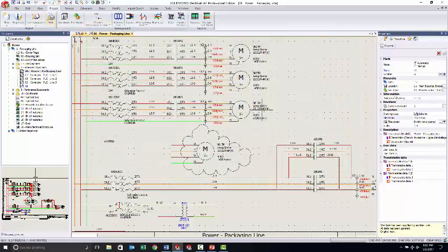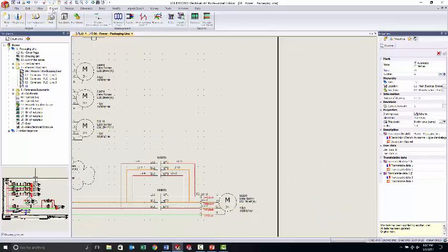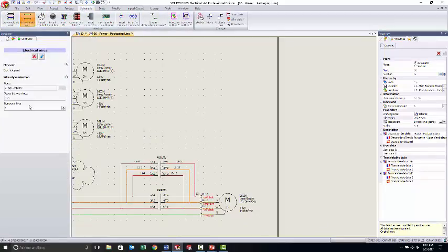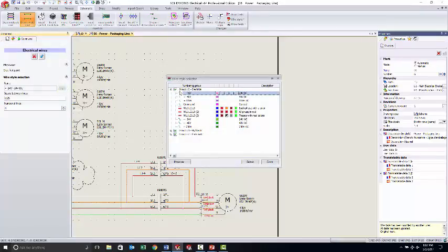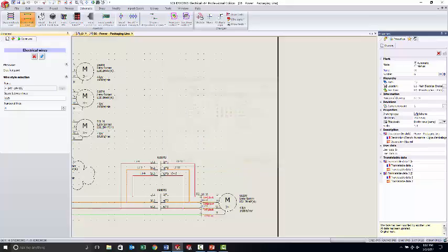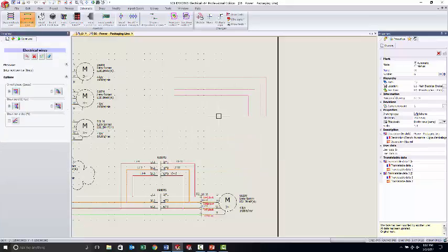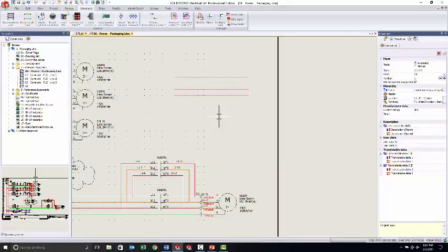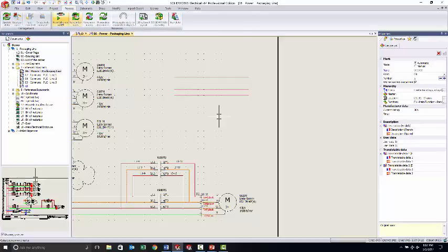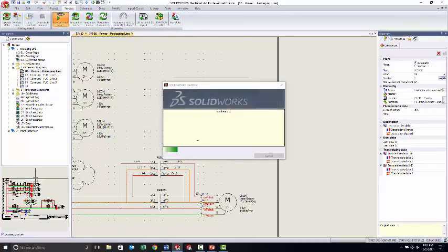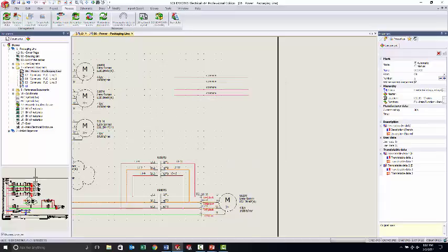So now when I go to use that, if I draw a schematic, I'm going to draw multiple, let's draw 4 of them, of that 24 volt, and actually say project process, number new wires. All right, they all say common.